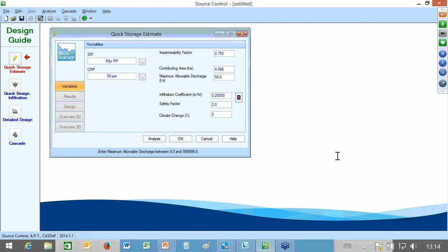Now, when you site your structure, what would the consequence be of it flooding? The lowest factor of safety, which is the next cell I'm looking at, is 2 that we would recommend using in the program. You can see at the bottom it's saying you can put anything between 1 and 50. That's what we would allow you to input into the program, but we would recommend at least a safety factor of 2, and then it ranges up to 14 depending on the severity of flooding. So if you sited your structure and it flooded and it adversely affected the entrance to a business, then that would be a safety factor 14. We run through this in the training courses. That's all we need to add in here.